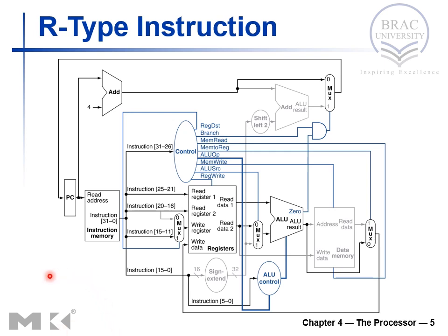Now, for R-type instruction, as we have discussed previously, it is always a good decision to design a generalized circuit where just by changing the control signal, we could enable different components, but the same circuit can be used to execute different instructions. Here, for example, we have R-type instruction. We could see here that some of the components are really light. So these are the components that are not used for executing R-type instruction.